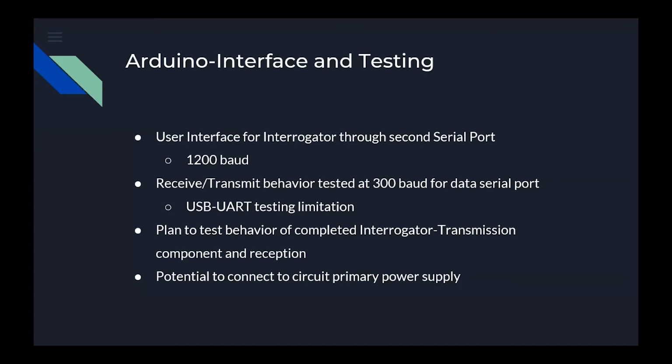Plans for the future include linking an interrogator board to our transmitter circuit to determine if it will broadcast correctly. We also plan to test if the board can be fed from the same power supply as our hardware circuits, or if it will need a separate supply, or battery. Lastly, we intend to test if the data transmissions function properly at 400 baud linked to our completed hardware.